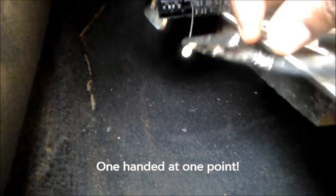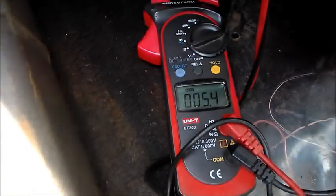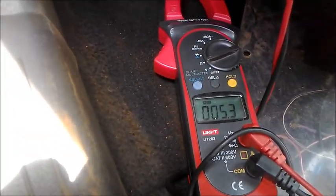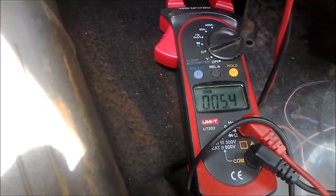So I'm going to move my pin to terminal 16, which is that one. It is difficult to do that with one hand because the other one is holding the camera. But I've managed that. And as you can see, I get the same reading. So those solenoids are fine.